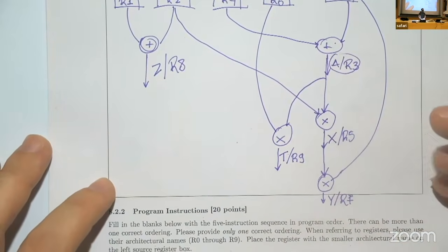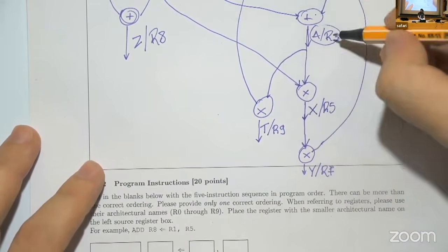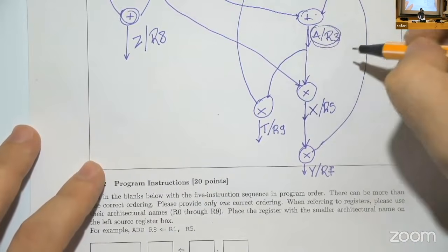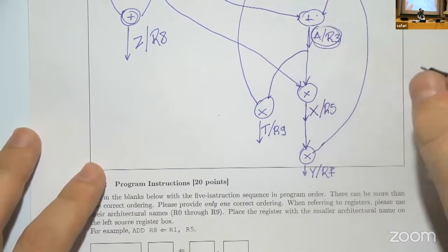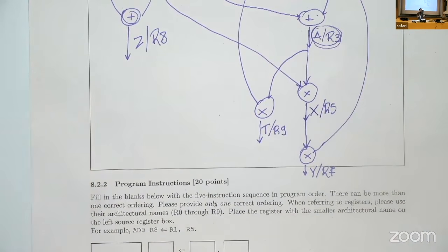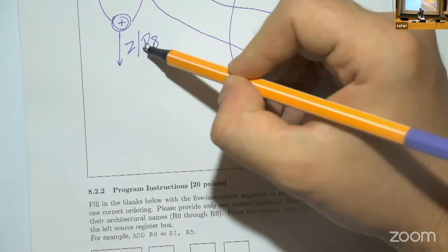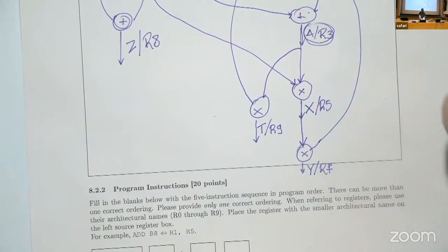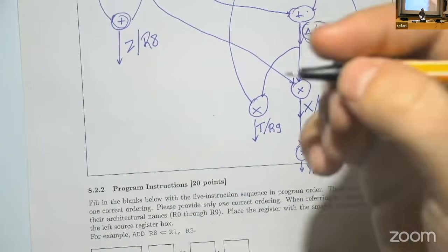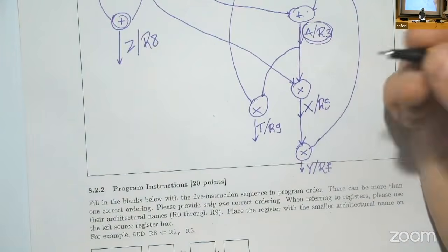If it can be the first instruction, then when do we come up with the result R3 from adding R7 and R4? Is that possible? The result of R3 is not in the reservation stations. So this is not possible. If you add R1, R2 to the destination register R8 first, it's wrong. That's not possible, because we don't have the previous instruction, which is R3 from R4 and R7, inside the reservation stations. So don't be confused with that.